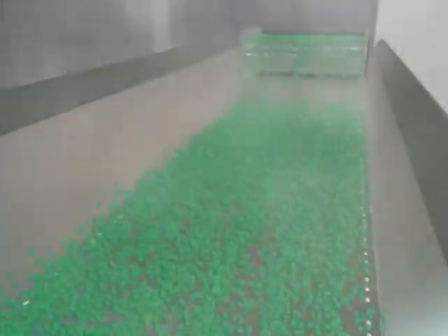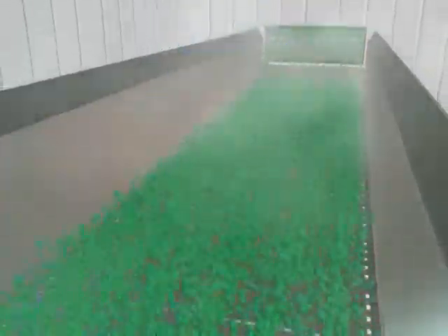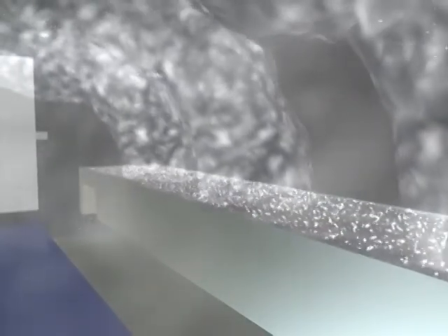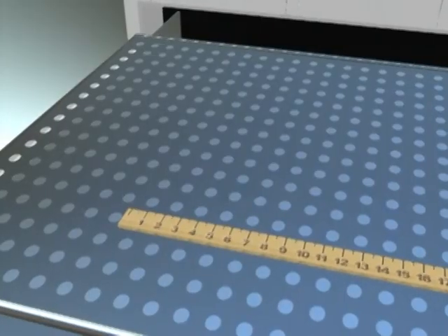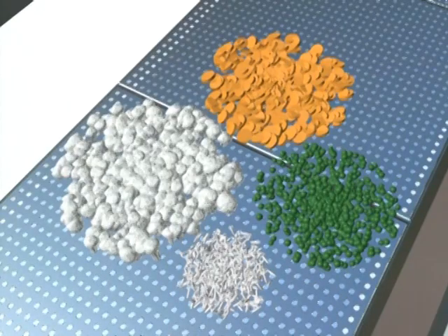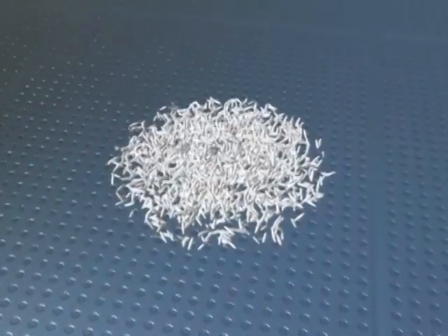Some of the benefits are: compared to the belt system, the airflow is more evenly distributed. Therefore, the tray freezer will provide complete separation and even freezing quality. The snow belt for the fluidization tray freezer can extend longer production times without defrost. The hole size for each tray plenum is designed with variable hole sizes for various types and sizes of product. The fluidization tray freezer is the only freezer of its kind that can freeze small 1/8 inch diameter product such as rice.